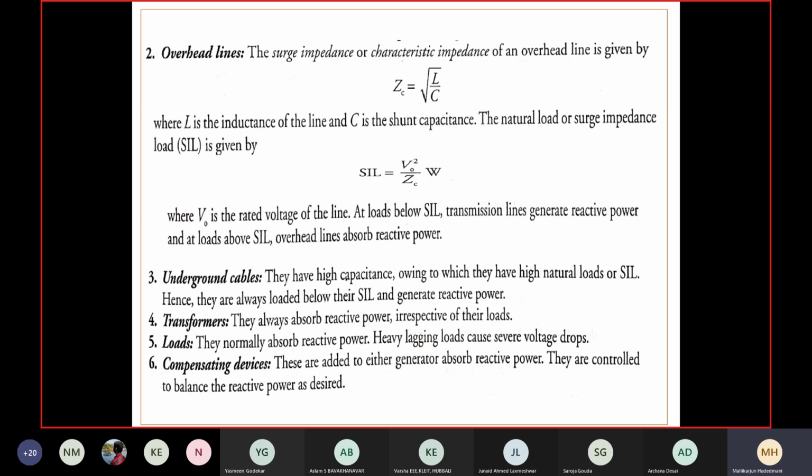If the system is suffering voltage drops, in very serious terms voltage collapse, a rapid drop of voltage due to rapid change in load on the system, that kind of phenomenon we call voltage collapse. Collapse in the sense of suddenly falling to a very low value which cannot be controlled or recovered. That kind of phenomenon leads over time. Once we see a drop in voltage, there is further drop as the load increases. So if the system is not able to make adequate corrections, voltage collapse is possible. That will be studied as the stability aspect of the power system.